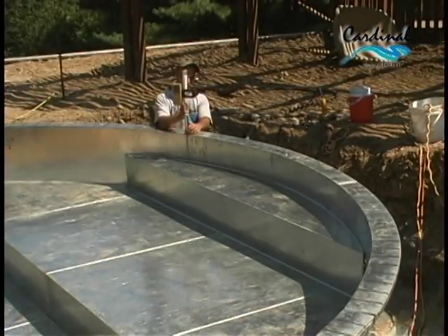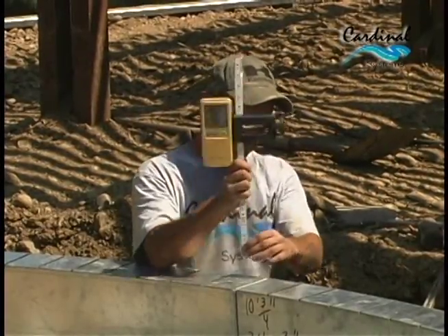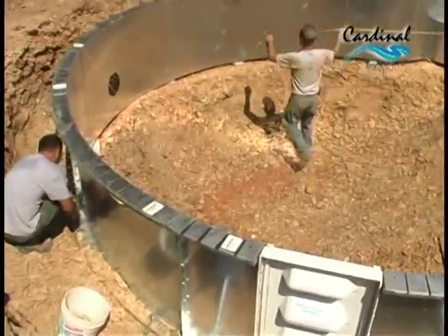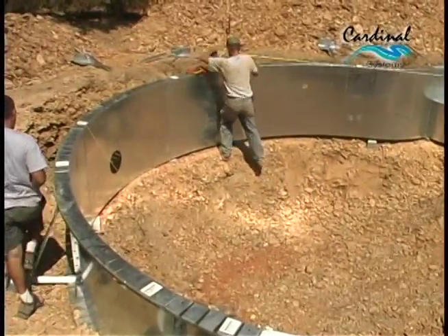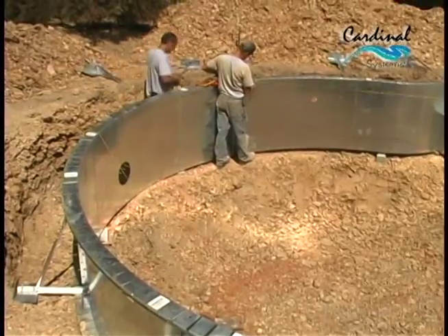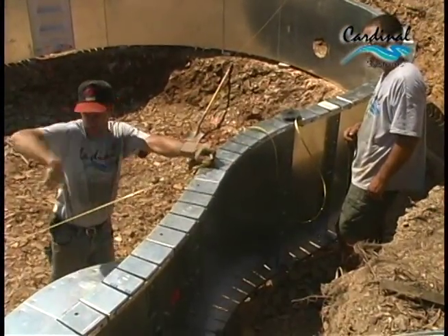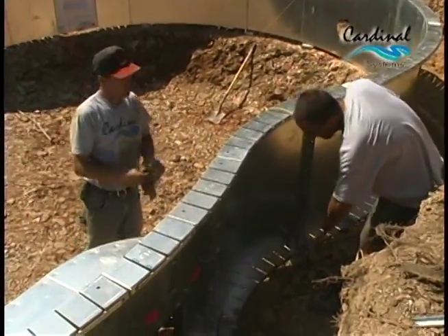With the assembly complete, you'll also want to check to ensure the structure continues to be level. Continue going around the pool wall, confirming alignments and ensuring that the structure is level, staking it as you go. Make corrections as required and secure with rebar as you proceed.